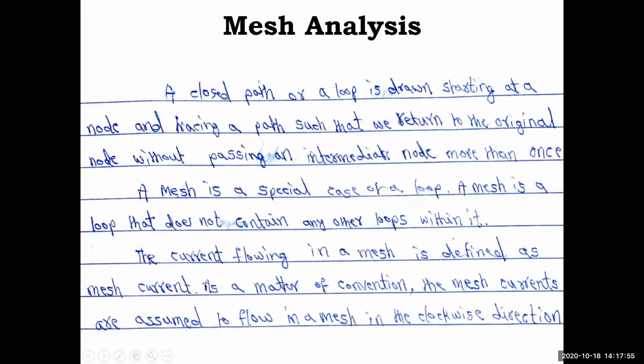Before that, we try to generalize the theory part of this mesh analysis, and how basically we'll write the mesh equations. That is very important. Once you know how to write the mesh equation, you can be given any problem and you are able to do it. Based on the topic, a little bit of variation will happen in the mesh equations, but first, given a basic network, how to write the mesh equations. That is our intention.